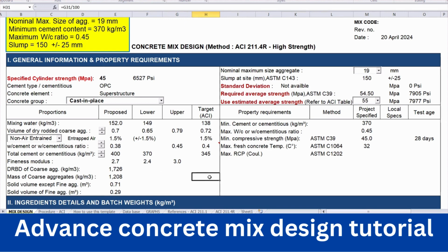I would like to share with you also that you can actually use as low as 130 kg of water or 135. Normally I am playing on this water. The reason is that during summer you have to add ice, so you need some more margin for the ice quantity, and that's why I prefer 130 kg of water, the lowest possible, or 135. So far this is working for me, so I'm suggesting it to you.